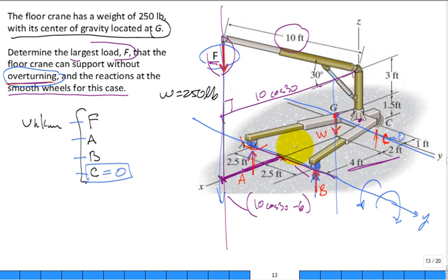And then the moment arm distance for the weight that goes through G around this axis is, what's that distance? I think they give it to us, 4 foot right there. Isn't it? 4 foot. All right, is that how you solve for F? Yep. Okay, and then you got for F a value of 375-ish pounds.